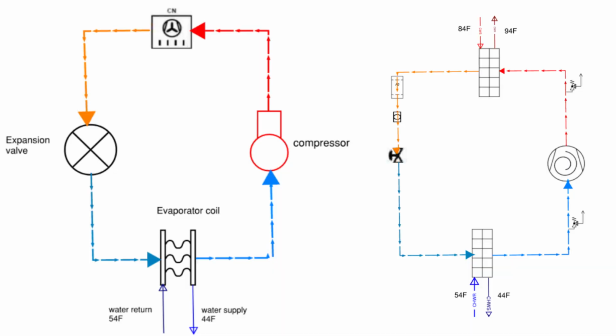They can be air-cooled or water-cooled and operate on the vapor compression cycle. Inside every mechanical chiller, 4 components form the core: the evaporator, where water gives up its heat to refrigerant; the compressor, which raises the pressure and temperature of that refrigerant vapor; the condenser, where that heat is rejected to air or condenser-water; and an expansion device, which drops the refrigerant pressure before the cycle repeats.